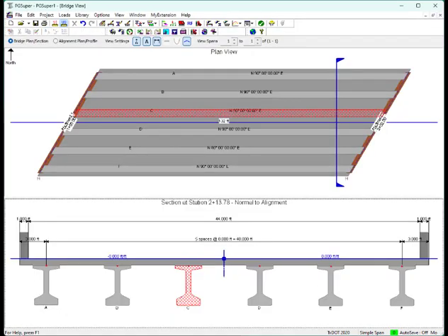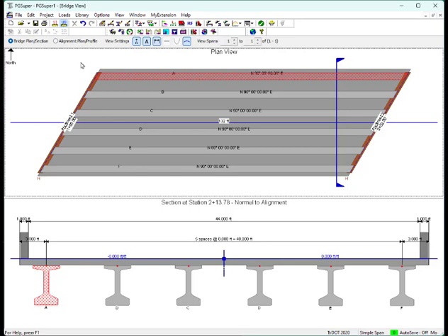As you can see, all of the girders in our make-believe bridge are the same length. When this is the case, you should strive to make all of the girders identical for ease of manufacturing and construction. But we know that dead loads and live load distribution are unique for each girder, so we need to determine the controlling girder. An experienced engineer can often determine this from examination, but another method is to simply run the design algorithm on all girders in a span. To simplify our discussion, I'll only run the algorithm on girders A and C.